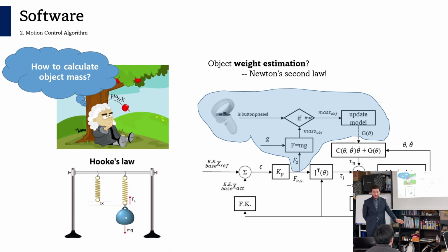While carrying heavier objects, end effector doesn't follow reference pose accurately. This phenomena is the most relevant for up, aka Z direction. In order to reduce this pose error, we need to increase the virtual spring stiffness, aka task space Kp gain. But this method has its cons. Most importantly, whole manipulator becomes stiff and compliance fades away. Means the motion is not safe anymore. For this reason, I had to think differently.